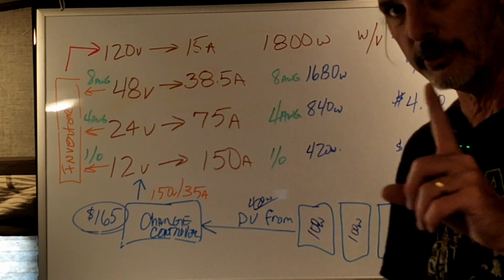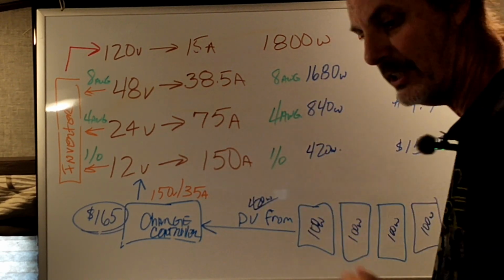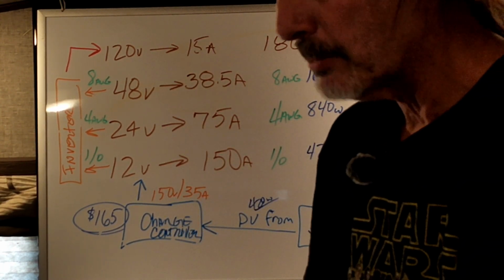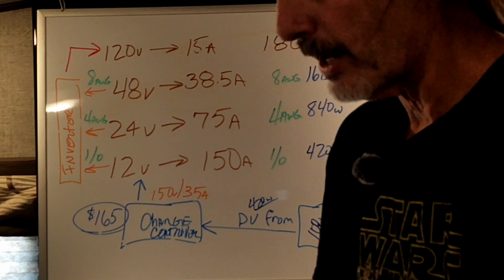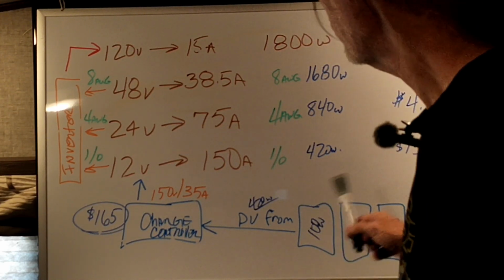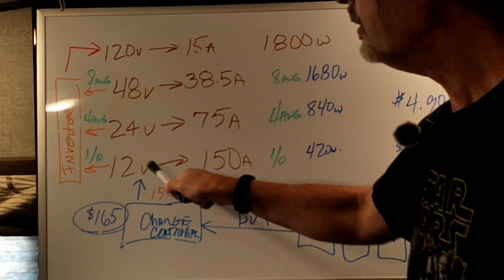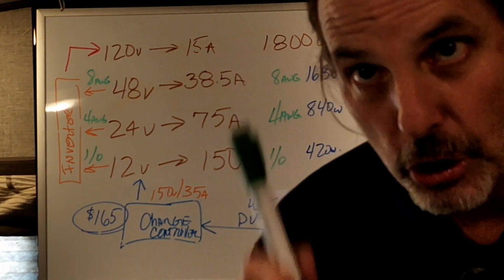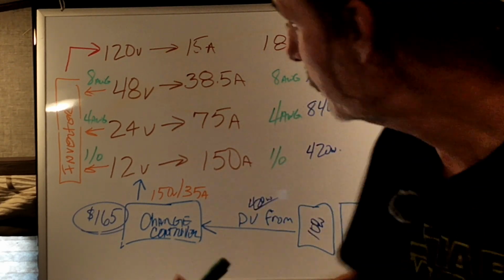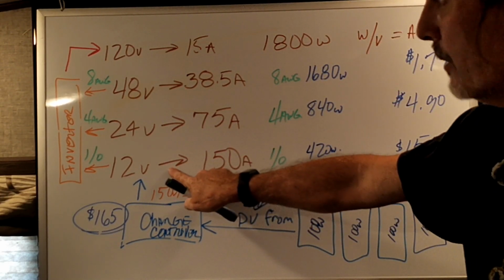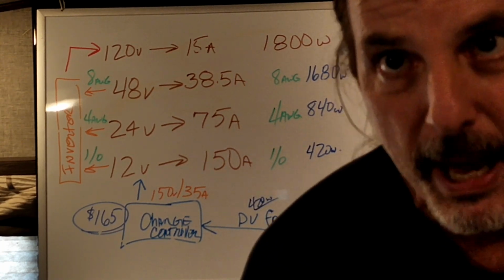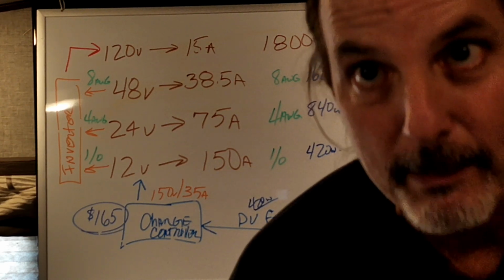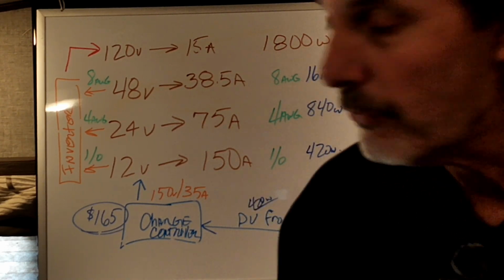And then you also have got to consider that when you have 1500 watts going into that 12 volt battery, you got to look at the maximum amount of amperage. 1500 divided by 12 is 125 amps going into this battery, and you need to be very careful that you look at the battery's maximum charge rate, because chances are one battery would not do that. It would mean that you're going to need multiple batteries, you're going to need to add bus bars to your system, you're going to need to have more cable, more expenses, and so on and so forth.